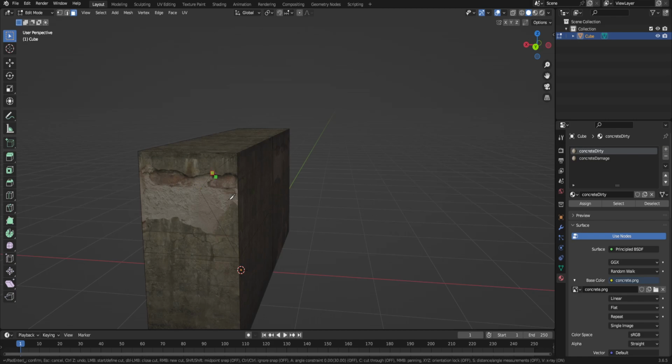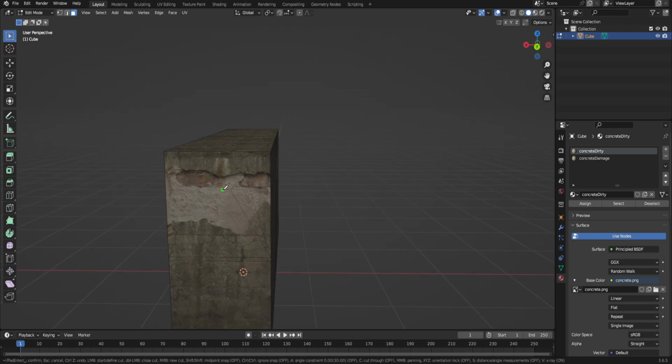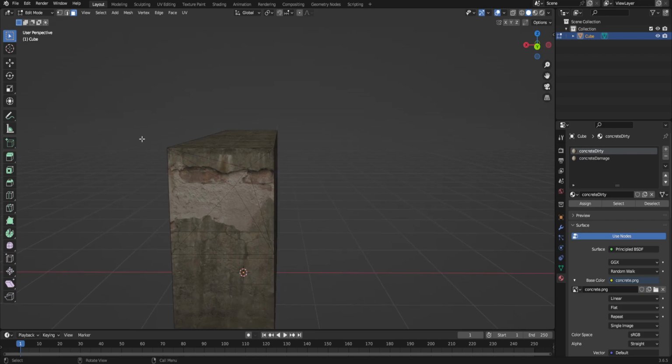Now you have to be careful doing this because it can get out of control. You want to make sure that if you do start cutting in, you feel comfortable doing so, because it does add some weird wireframe to your model. Like you can see how weird it is, but as long as you tie it into the edges, it should be okay. And I do stuff like this more as a finishing sort of deal.